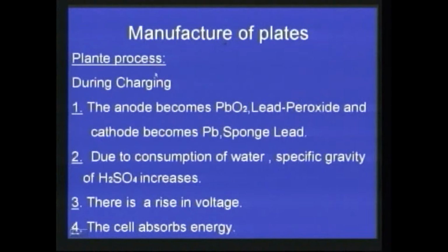During charging, the anode becomes lead oxide or lead peroxide and the cathode becomes sponge lead. Due to the consumption of water, the specific gravity of H2SO4, the electrolyte, increases. Here there is a rise in voltage. The cell absorbs energy.